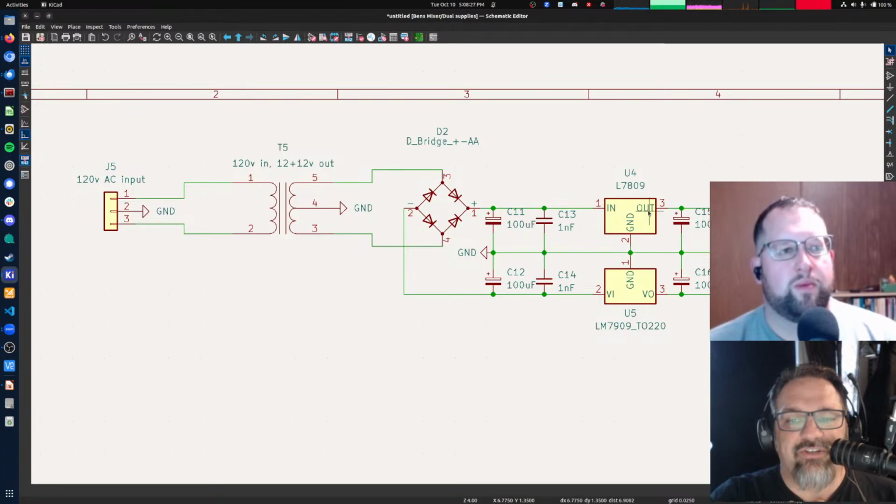And then as long as you're not drawing too much current through this, these things won't overheat because you'll have to dissipate whatever the input voltage is minus the output voltage. That amount of voltage is getting dropped through this component. So let's say the input here is 17 volts and your output is 9 volts. You're dropping 8 volts across here.